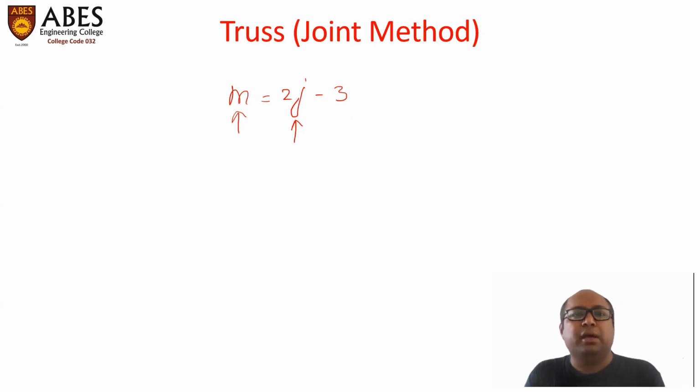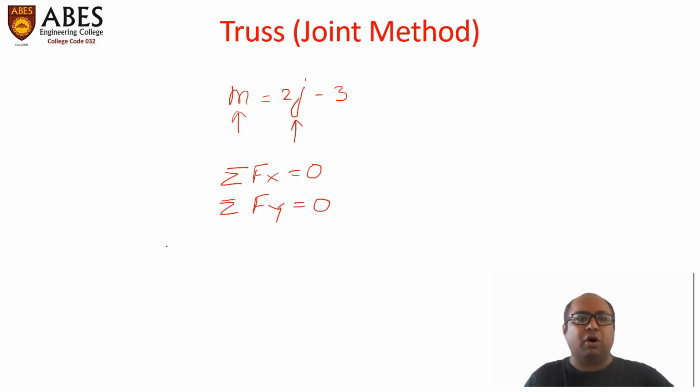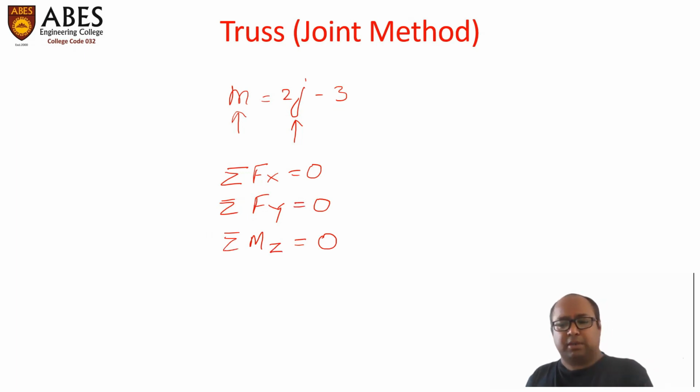The force system will be a coplanar non-concurrent force system, and therefore the equations of equilibrium are of the type: sum of all forces in the horizontal direction, sum of all forces in the vertical direction, and sum of all moments about the axis perpendicular to the plane must be equal to 0. Why is this so? Because we are working in a coplanar non-concurrent force system.